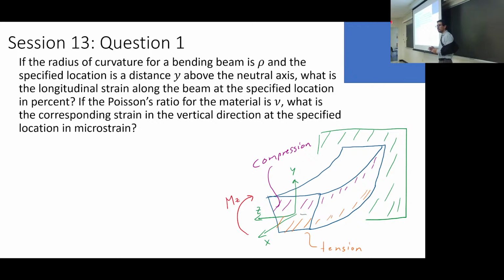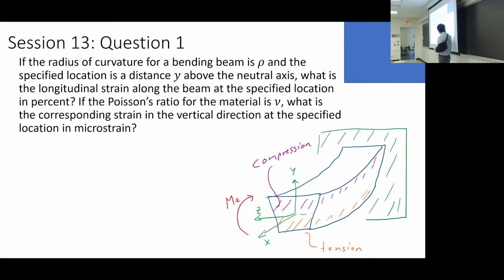Like, oh man, what's up with that? Well, look, and I try to exaggerate here. If the top is in compression, right, that actually means that the top portion is going to get a little wider. Why? Because I'm bringing it closer. Just imagine that I've got a beam, a bunch of bars, right?